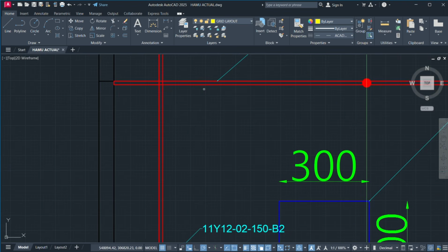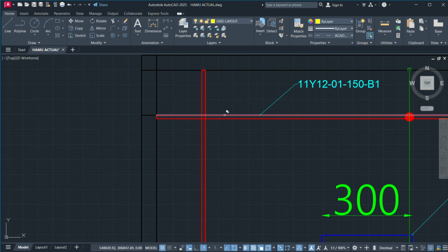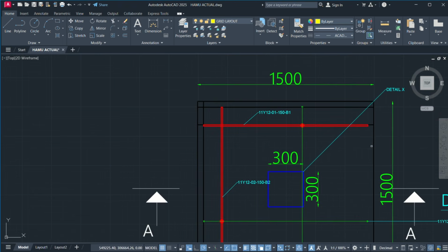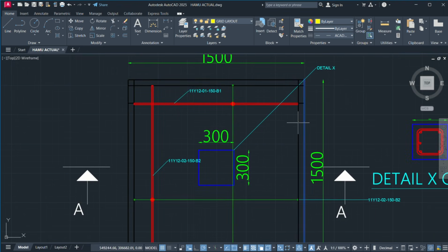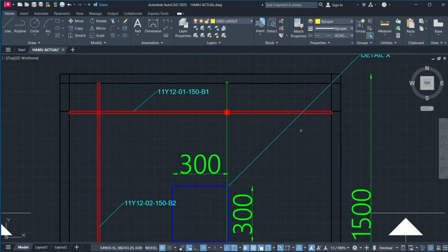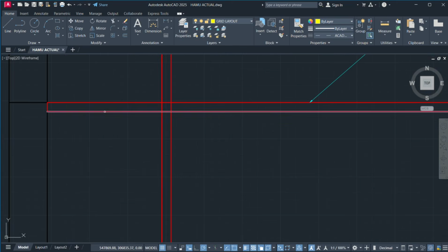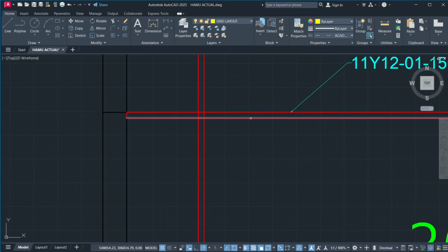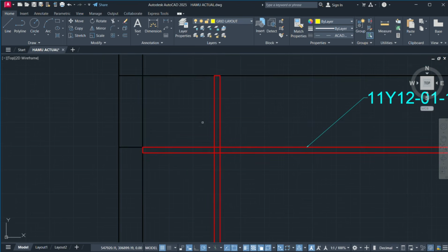Then when you're done with drawing this, now the rebars again, I should make mention to say, when you draw a line that is straight, remember that this side you're also supposed to have a what? A concrete cover of 50. So let me just do another offset just for clarity's sake to say this side I'm going to have a 50. Now when I do a 50, you've seen this is where the bar is ending. So as a result, now the main focus point is that your rebar should not just be one straight line. You actually need to show its diameter. So since this is a Y12, you are going to offset the line that you're going to draw from this end of the 50 to the other end of the 50. That is going to be offset by a distance of what? 12. When you offset it by a distance of 12, it's going to look something like this.